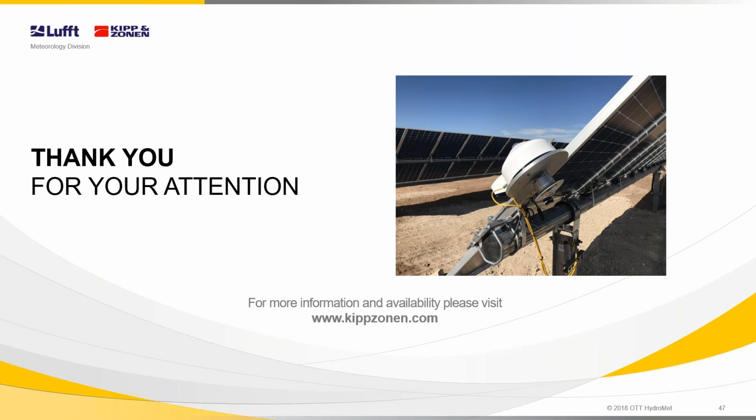Got you. So we still have time for a few more questions, and this is the next one. Can a solar reference cell be used for measuring rearside irradiance? Yeah, this is similar to the previous question. The standard tells you that you can measure it either with a PV reference device or a pyranometer, and it depends again on what you want to do. We think that a good way to measure irradiance, if you want to measure all the irradiance there is, is to choose a pyranometer as your measurement device.